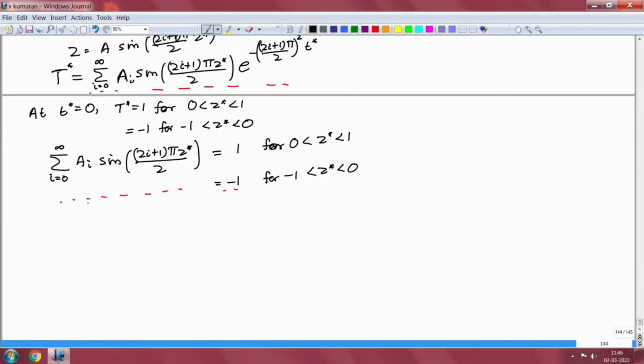The value of the constant is determined from the homogeneous boundary conditions. In this case, the homogeneous boundary conditions are 0 flux conditions or 0 derivative conditions, in contrast to the previous case where the temperature was 0. And because we have a discrete set of values for beta, we can solve for these, and I will complete the solution in the next lecture using orthogonality conditions.